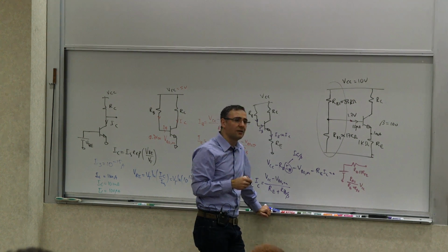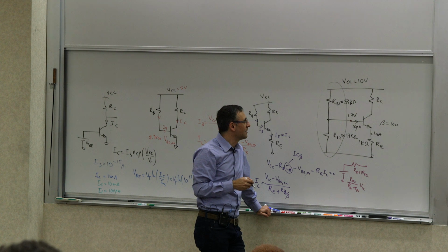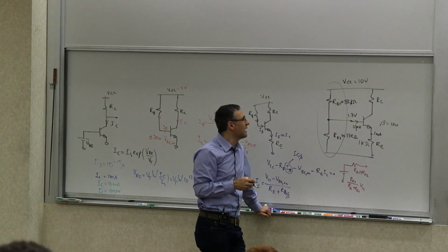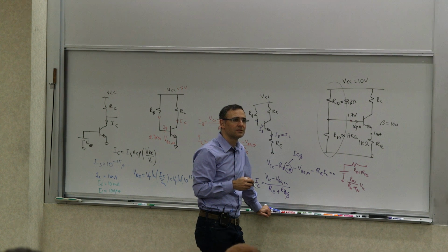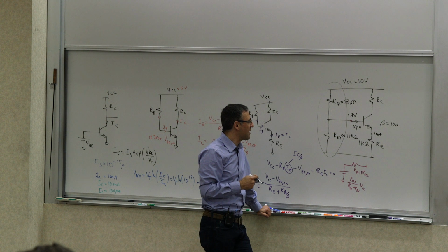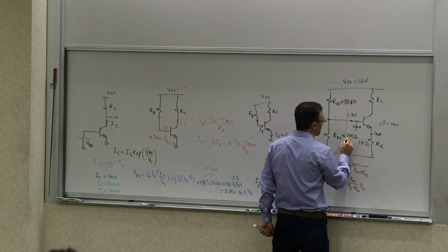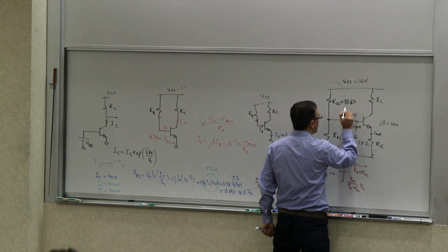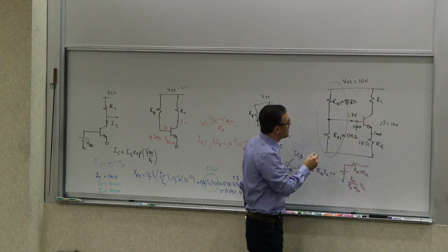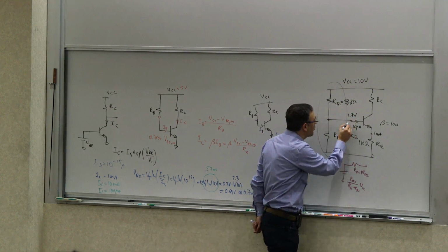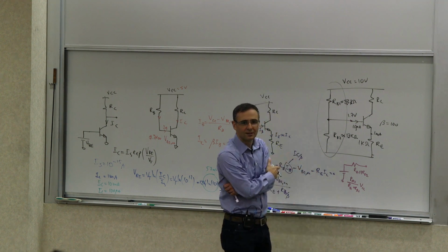So micro and kilo give you a milli. So you will get 830 millivolts, right? That can be significant. So you may want to actually reduce these. Instead of making them 83 and 17, you make them 1.7 and 8.3 kilo ohms.